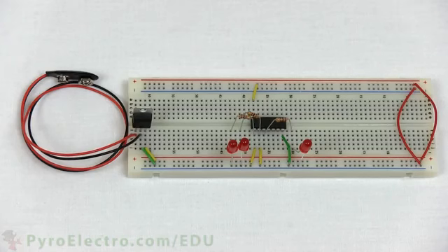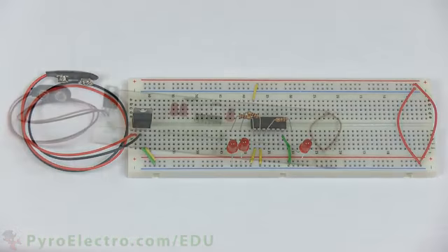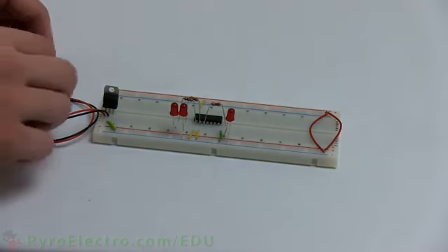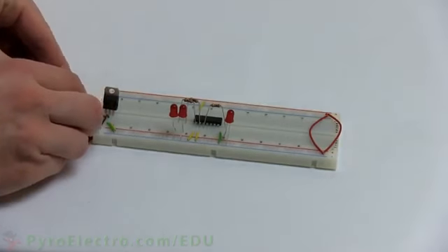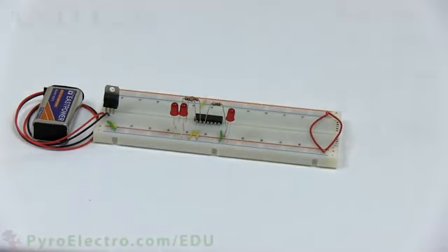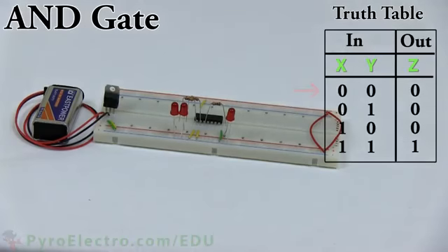If an input or output to or from the AND gate is a logic 1, the LED will turn on. If it is a logic 0, the LED will be off. With the battery plugged in, the system is turned on. The 2 yellow wires will be used to change the state of the system. The first state that we're looking at right now is input of 0, 0, which yields an output of 0.